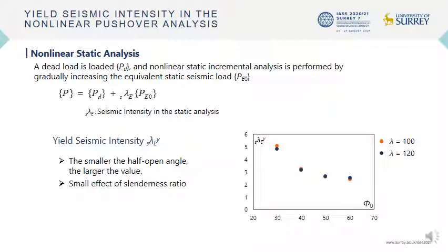This figure shows the relationship between yield seismic intensity and half-open angle obtained by nonlinear static analysis. As shown in this figure, the yield seismic intensity is larger for smaller half-open angle.